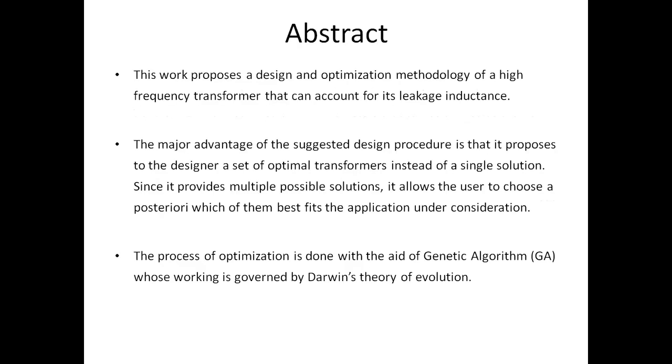This work proposes a design and optimization methodology of a high-frequency transformer that can account for its leakage inductance and losses. The major advantage of the suggested design procedure is that it proposes to the designer a set of optimal transformers instead of a single solution, since it optimizes not one but various parameters.